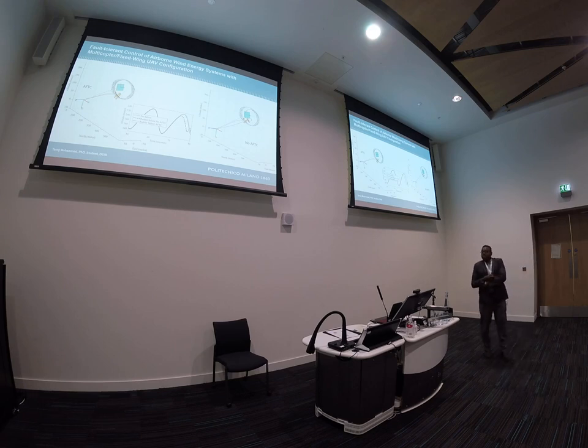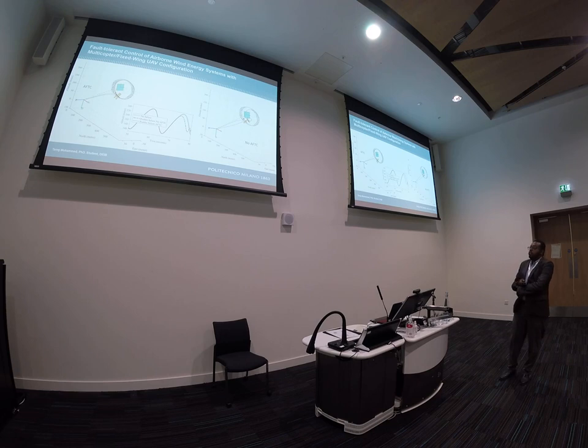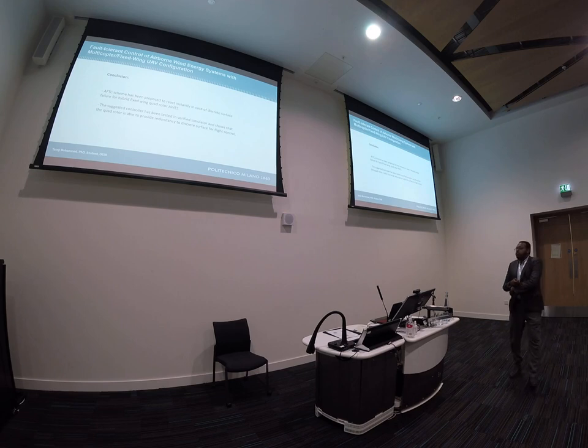You can see here the altitude in the dashed gray line starts to decrease and loop and then goes down. But when we apply active fault-tolerant control, the VTOL system is able to follow the same trajectory as normal flight.